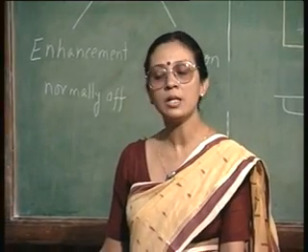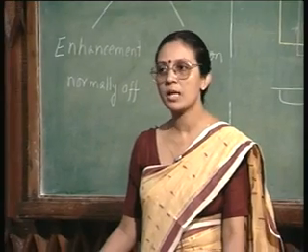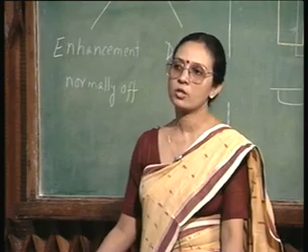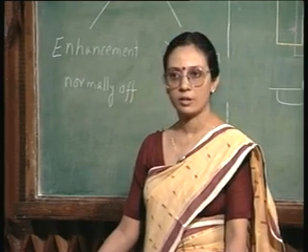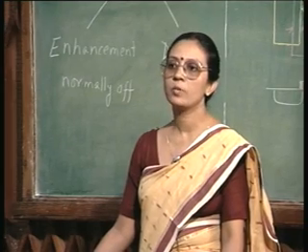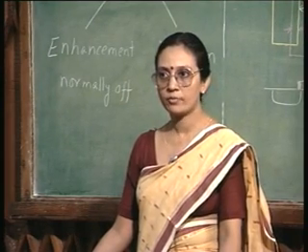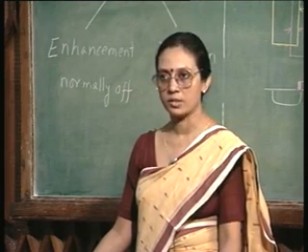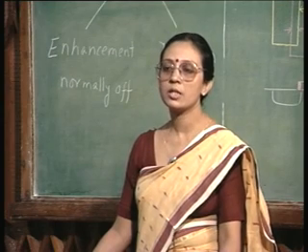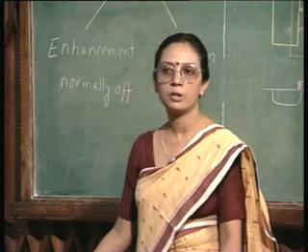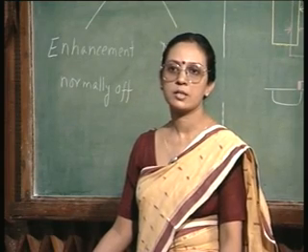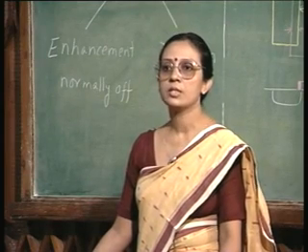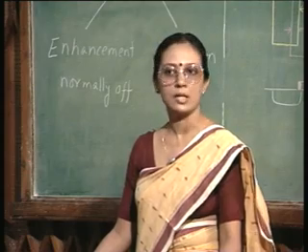In the metal gate, this problem comes about because we have to do the source and drain doping before the gate oxidation. The gate oxidation has to be the pre-final step immediately followed by metallization. This is because we use aluminum for all the contact metallization, and you know aluminum has a very low melting point. So, after you have put aluminum, you cannot do any high temperature processing, and unfortunately almost all the processes in integrated circuit technology need high temperature. So, for metal gate technology, gate oxidation has to be one of the last steps.